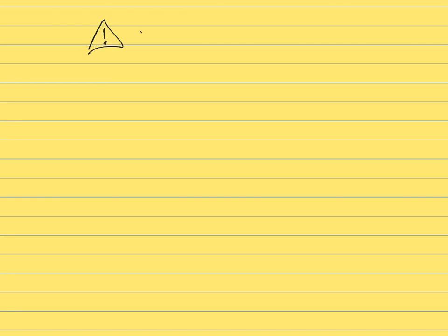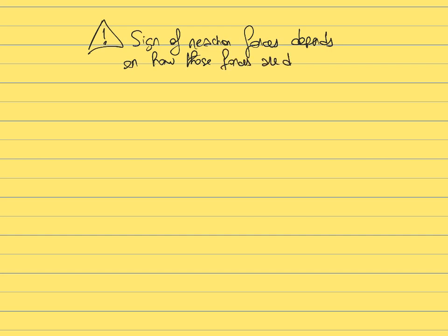Specifically, the sign of the reaction forces from the support depends on how those forces are drawn, how you define them. So that's something to keep in mind, which means that it is fine that in some cases, depending on how you draw them, you may end up with positive or negative unknown forces, but it doesn't mean that it changes anything regarding the physical reality of the system that you are considering.